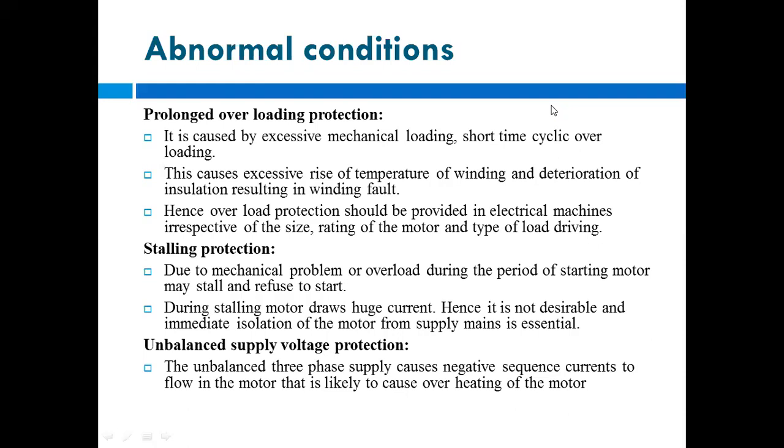Short time cyclic overloading means for some period you are giving that load, and then also your motor gets damaged. Then this causes excessive rise of temperature of the winding and deterioration of insulation, including resulting in winding fault.